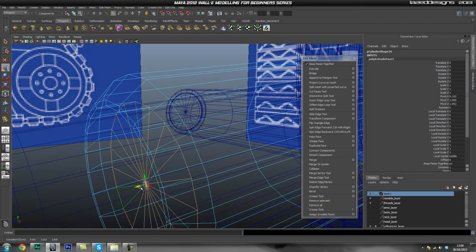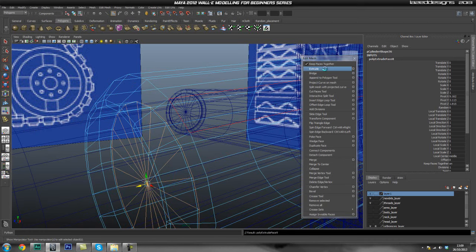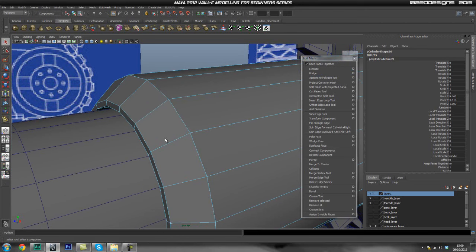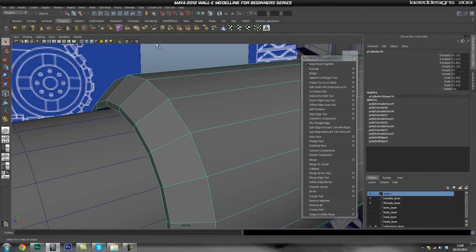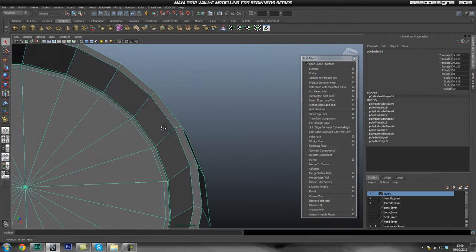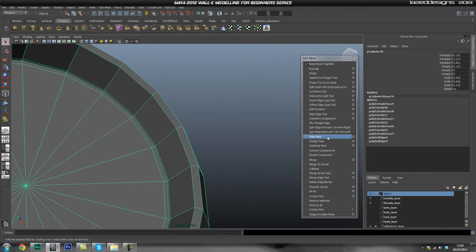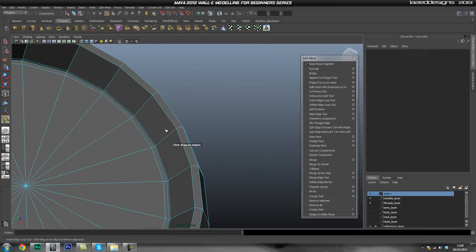So I'm just going to push it back roughly, go into my wireframe mode, extrude it one more time, move it back so I get that loop so I don't have to go in there again later, and extrude it one more time and scale it in. Okay, so that's great. And then now I'm just going to go ahead and isolate this piece to add in these edge loops that we didn't add. You could have added it while you were extruding as well.